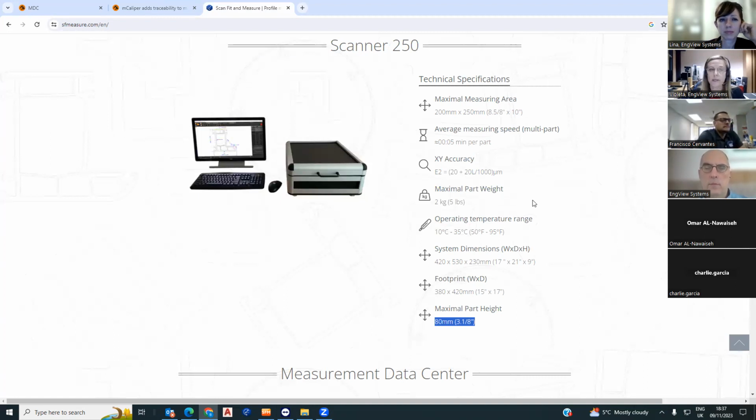We have customers with a very professional kit with manual files, and they use smaller, bigger ones, but it takes, for example, half a minute to prepare the profile for the measurement. Not more, because when you are experienced, you remove the burr on one of the sides, and half a minute is enough to prepare the profile. You can even do it in 10 seconds, but let's say half a minute for one profile to make sure you remove the burrs and the turnings. That's all. And then you will measure.